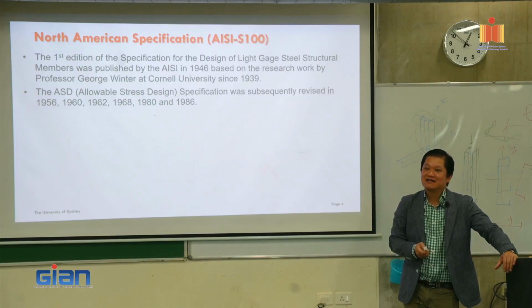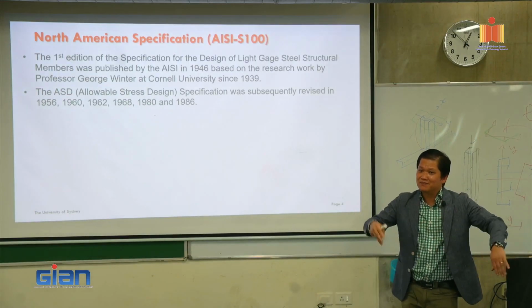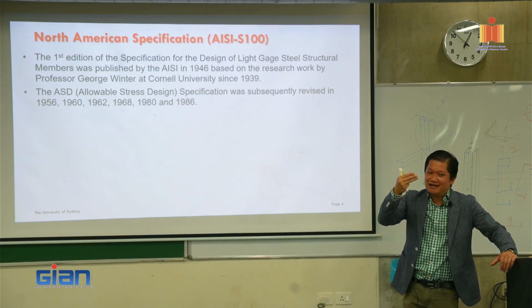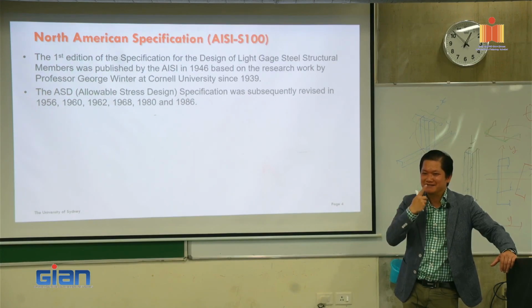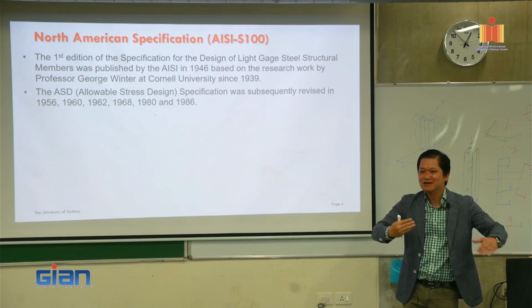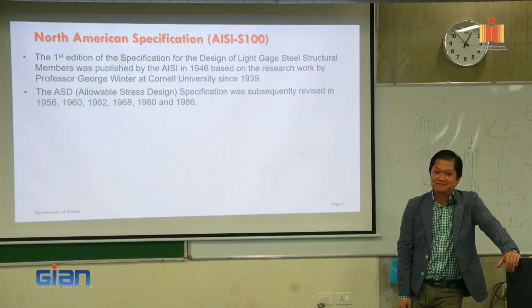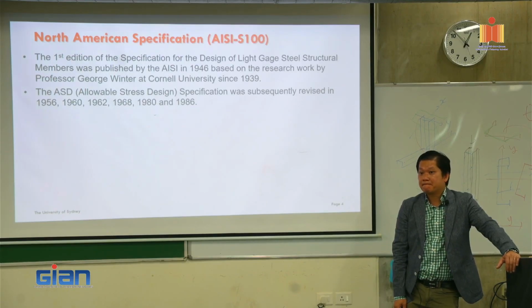Under the wind, it is a beam. For dead and live loads, it is a different case. If the load is going down, gravity, then it is not pure bending. Yes, another problem is biaxial bending. It's bending this way and a little bit the other way. It's actually very interesting. The load line is also not along any of the axes in the case of gravity loads. The section axis is not coinciding with the direction of the load.